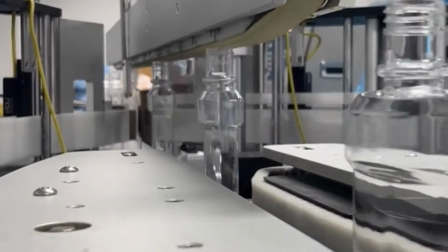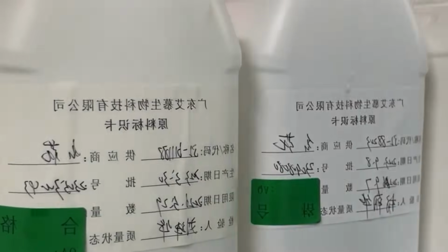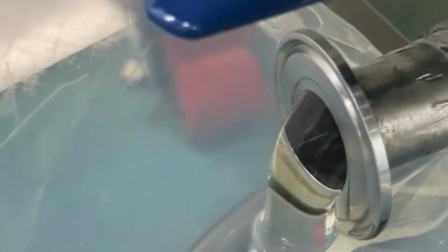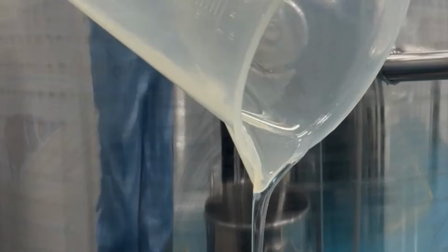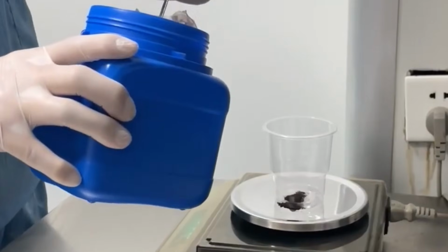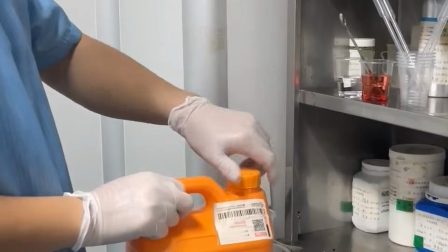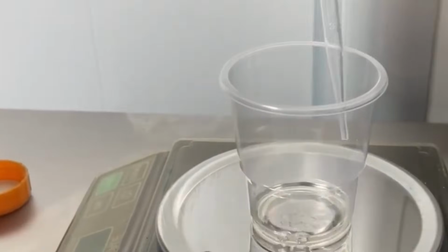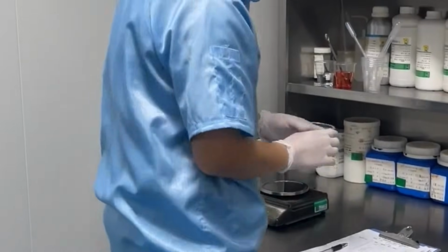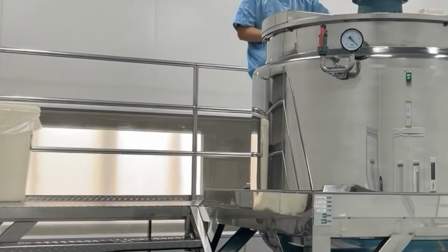These include dimethicone emulsions or food-grade silicone oils. Addition is controlled via gear pumps and only applied when foaming exceeds threshold levels, as detected by capacitive foam sensors inside the vessel. After full ingredient incorporation, the batch is subjected to a recirculation loop using a centrifugal pump system. The liquid is passed through an inline homogenizer or static mixer to eliminate stratification and achieve consistent texture and solute distribution.